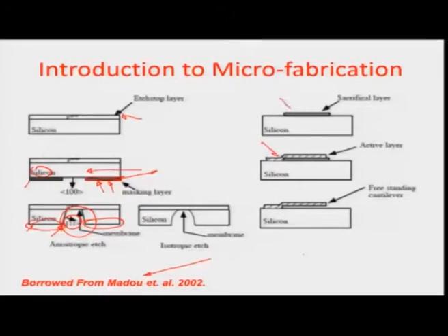all of which can be used in what we know as MEMS, or what we know as microstructures, which can then go into sensing and diagnostics. So, this again is a structure that I described to you before. There is a layer of material which is otherwise mechanically robust, but there is a polysilicon layer deposited on the top of this sacrificial layer which you are removing, and so out props this cantilever-like orientation of this particular material. So, this is how you make freestanding structures through microfabrication techniques.